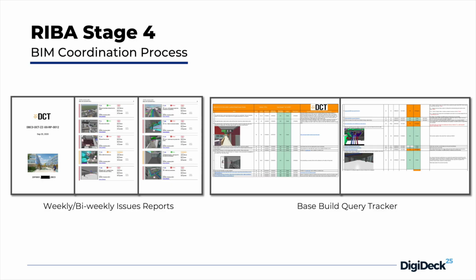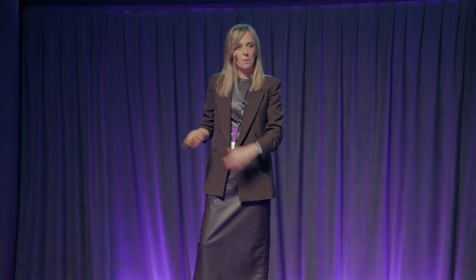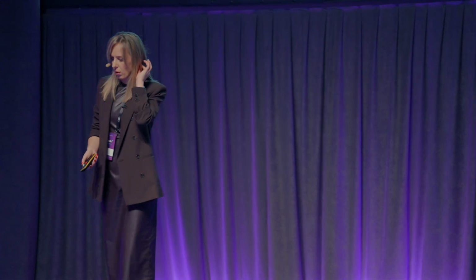When we are preparing for the BIM call, we are reviewing the federated model. It depends on the software that you are using. You can upload the federated model to the CDE, or you are using a live model, but you need to prepare the agenda. It can be issues or viewpoints that you are raising and that you will be discussing during the BIM call. Before the BIM call, you are issuing a report, just to let everyone know what will be discussed, giving them enough time to find possible solutions for the problems that we will be discussing, to ensure that the meeting is actually proactive and that collaboration is happening during the call.